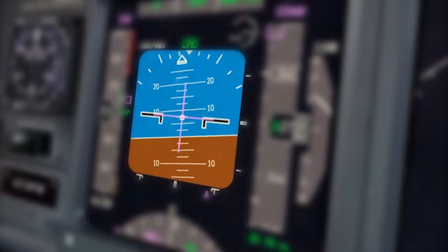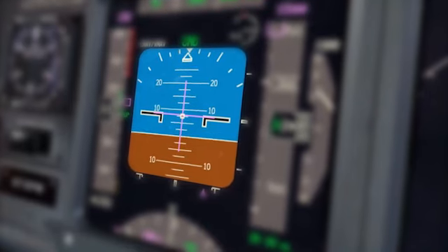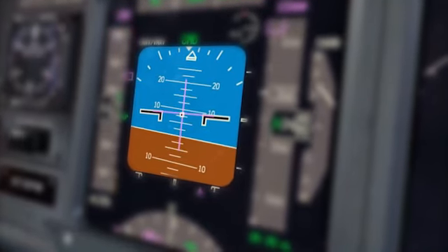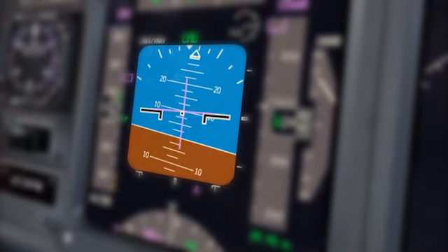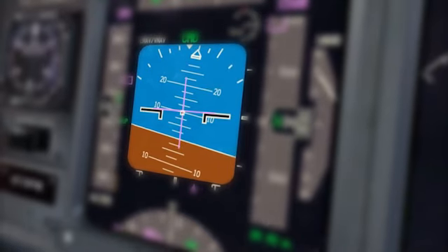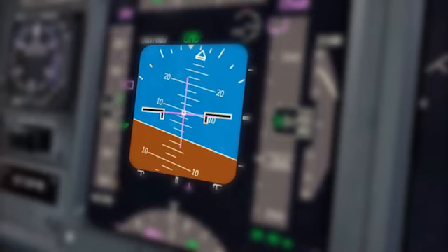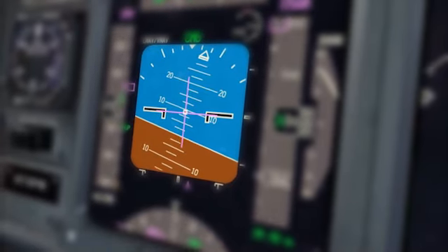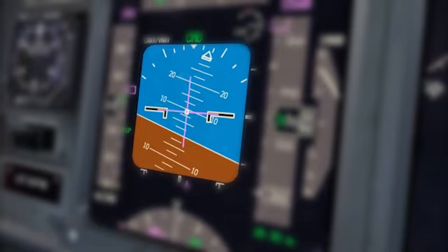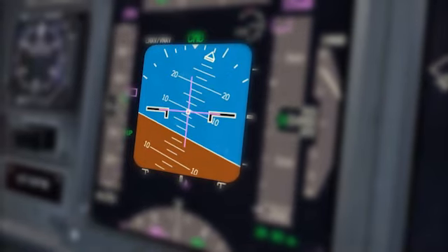In fact, the autopilot can be engaged with the flight directors in the off position, although this kind of situation is rare because of operating procedures that both we and the vast majority of airlines use, meaning flight directors are turned on at some point during the pre-flight and will remain so until at your destination.